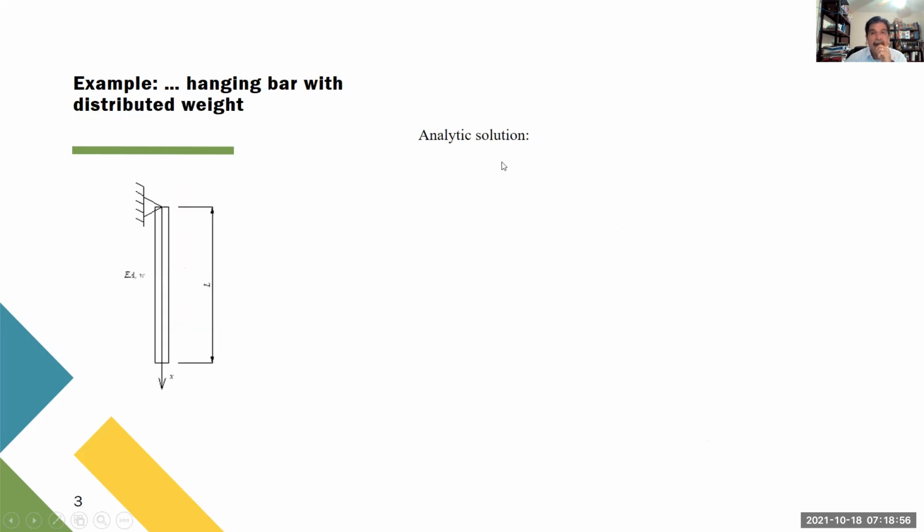Now, the analytic solution, that's easy. That's a second order differential equation. Two boundary conditions, it's a second order. One condition on the left, one on the right. Remember, this is the fact that we have no load here. So there is no load in this end, it's a free end. So the stress and the strain are 0. We can integrate that, and that's the result.